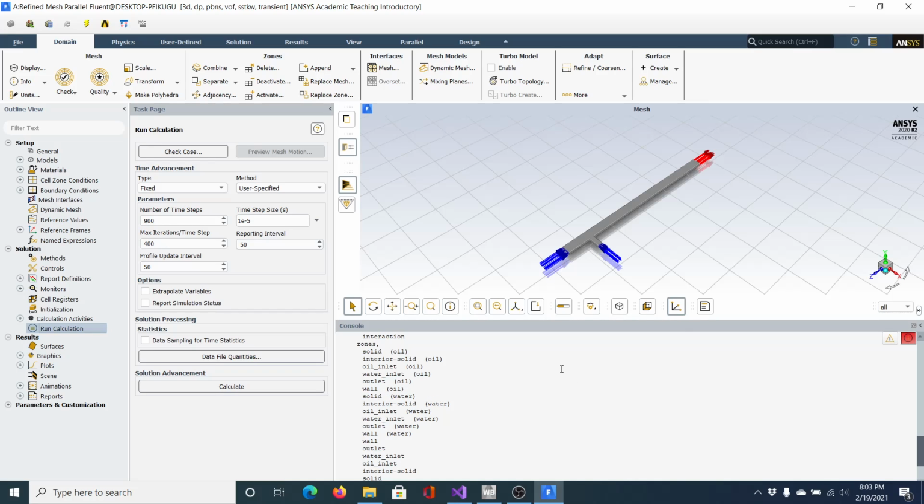That lets you know that at that time step the equations have run to where they don't have to run any more iterations. If you're not seeing it say converged and it's moving on to the next time step, it means you need to increase this number. The problem with that, of course, is it takes a lot longer.